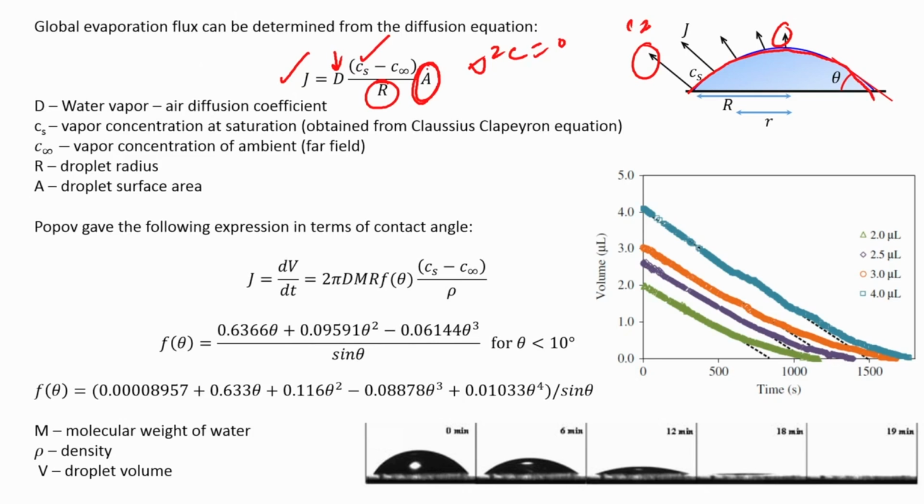So, just by using this relationship, this is a simple diffusion problem, right. There is vapor over here, this vapor has to diffuse out and that will control the evaporation rate, because, as we said earlier, that is the rate limiting step that we are looking at in this particular problem, got it, okay.